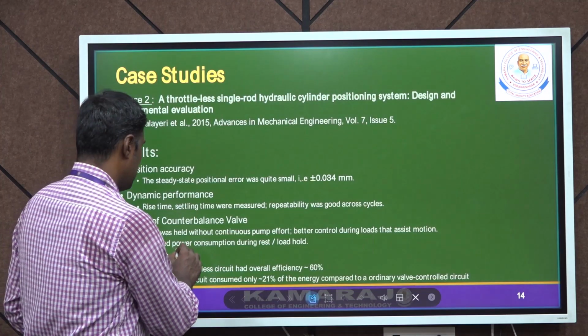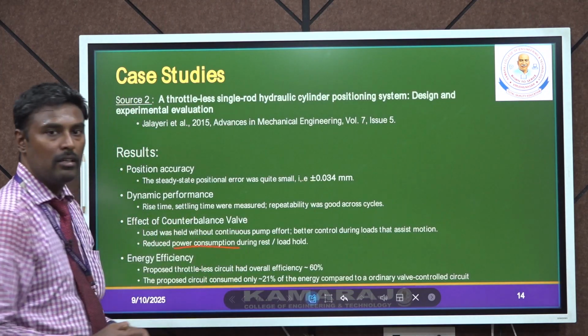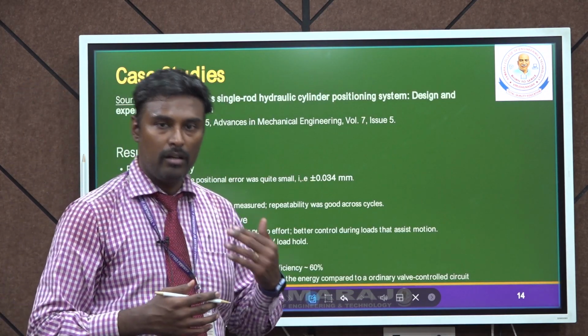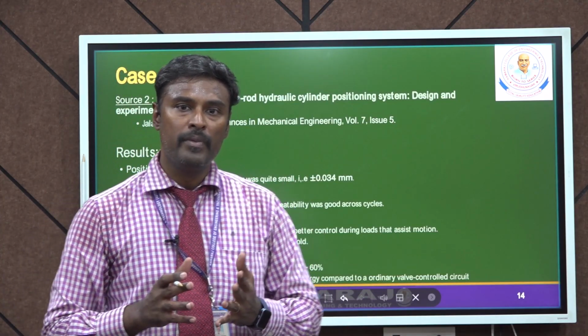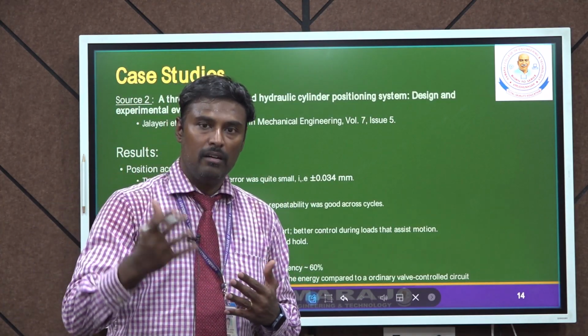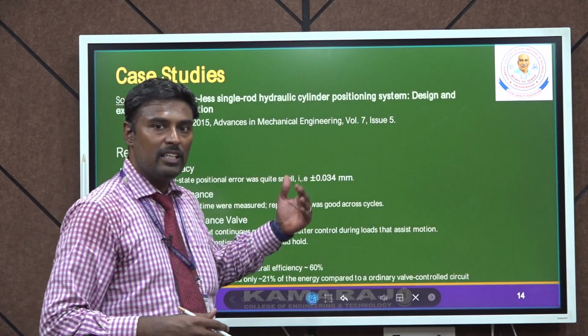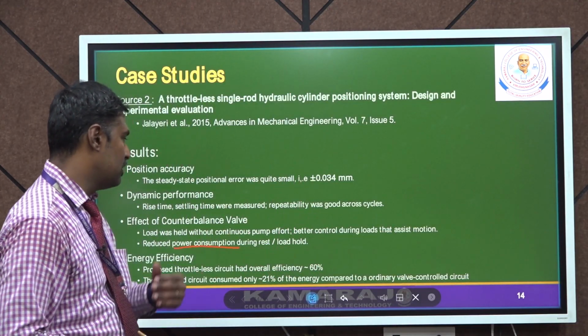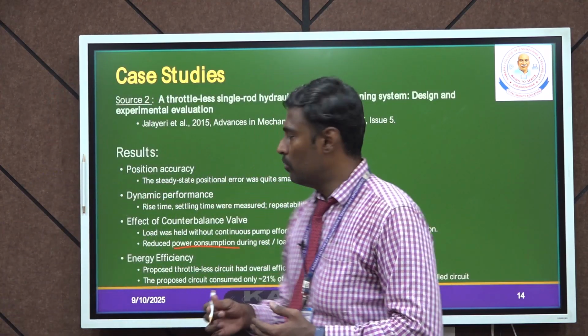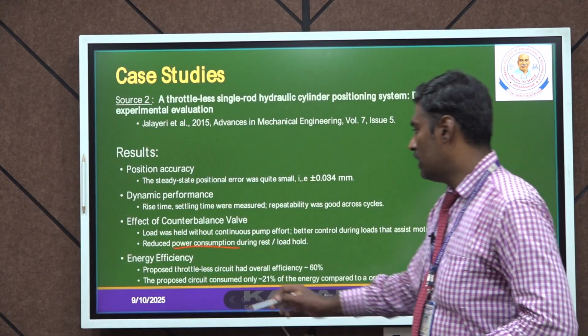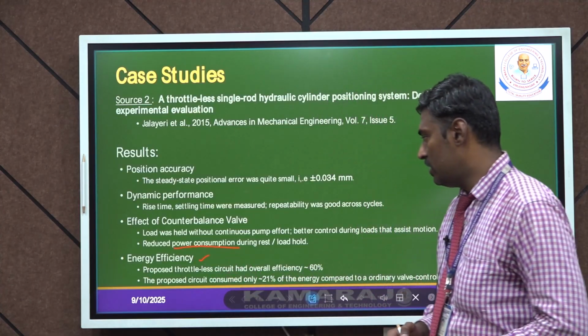In this state, the power consumption is reduced with the use of this counterbalance valve, because it will not make the entire pump operate for a long run. Therefore the running of the pump is reduced. Therefore the power consumption is less using this type of counterbalance valve, and therefore we can achieve high energy efficiency.